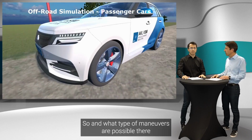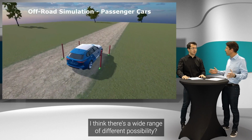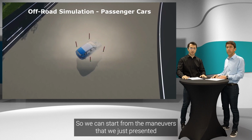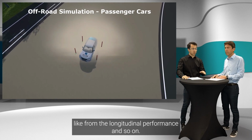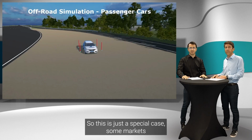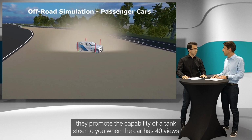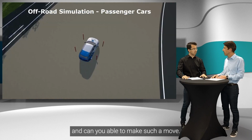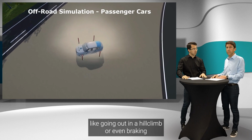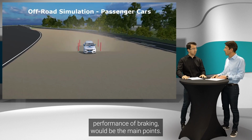What type of maneuvers are possible there, and what are typical use cases which are tested here? I think there is a wide range of possibilities. We can start from the maneuvers that we just presented, like longitudinal performance, up to the example now, tank steer. This is just a special case. Some markets promote the capability of a tank steer when the car has four motors and is able to make such a move. But of course, the traditional, normal use cases like hill climb or braking performance would be the main points.